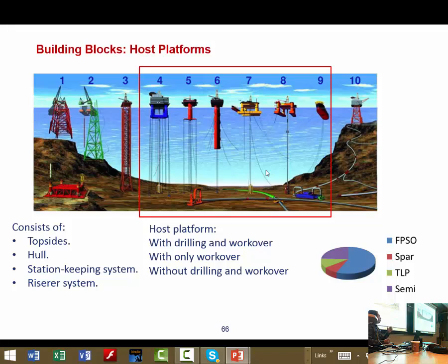This depends on the motion of your TLP. Because you have a pressure in the risers, and with the high pressure in the riser and the motion of the TLP, if you are still below the safety margins, you are allowed to leave the pressure of the reservoir to the top tension risers. But if your motion exceeds the safety limits, then you are not allowed to just put the total pressure of the reservoir to the risers. Because we're allowed to have a hole in the riser, we are not allowed to have a hole in the well.